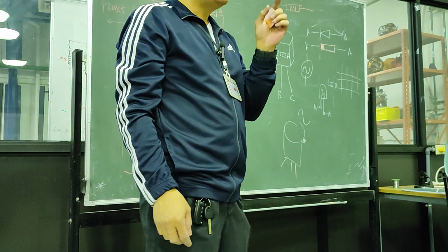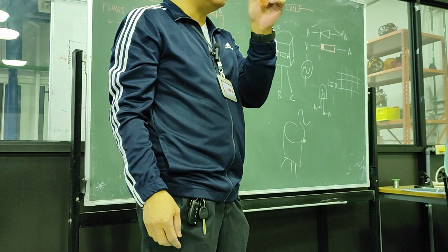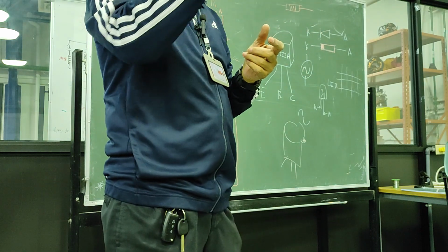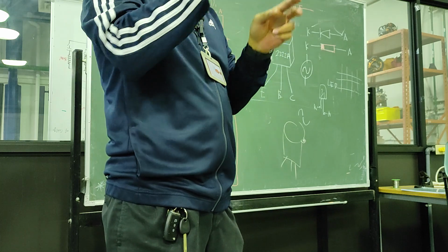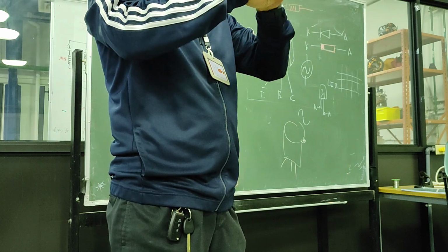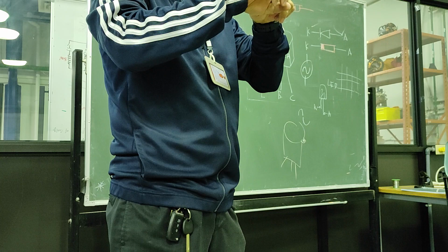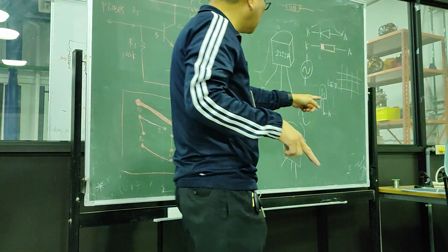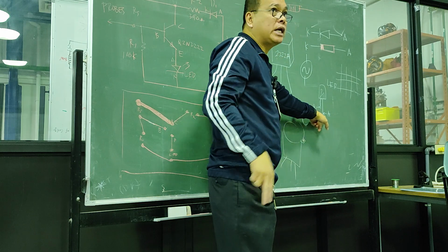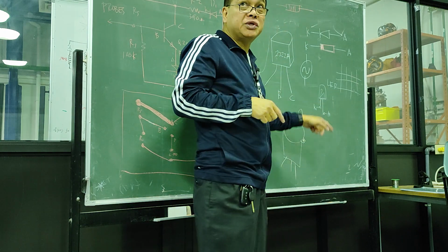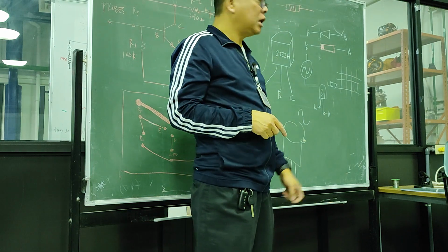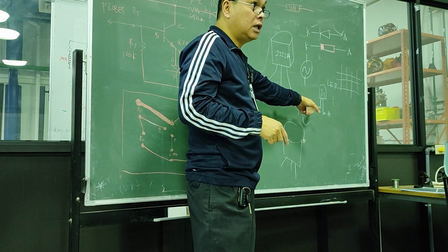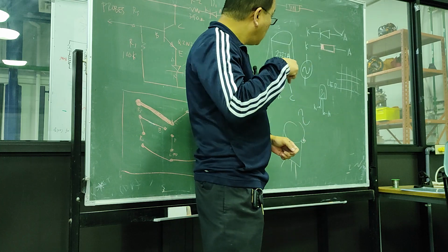Usually, when you are looking at an LED, there are two terminals, one long and one short. Usually, the longer one is the anode side, and the shorter one is the cathode side. So I'm drawing it and putting in all the information. Got it? Okay.